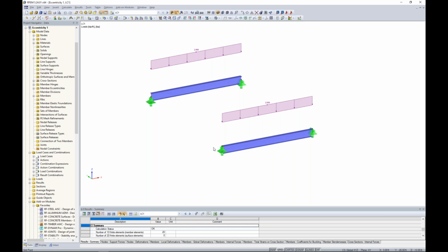But when we're talking about the finite element analysis software, this truly is what it sounds like. It's for the analysis, for the engineer. So it's not our goal to make sure that every element is lining up perfectly with every other adjacent element. Now, I'd like to take a minute to talk about when eccentricities can be helpful, but also when they can really cause unwanted behavior within the program.